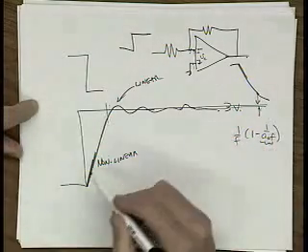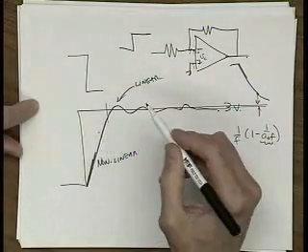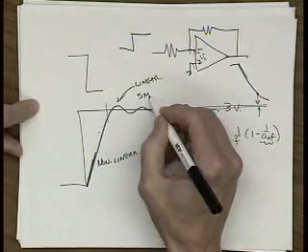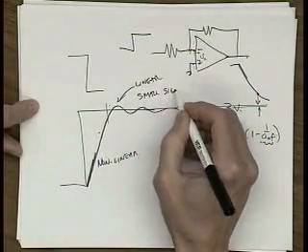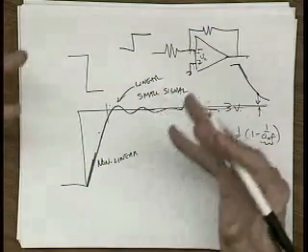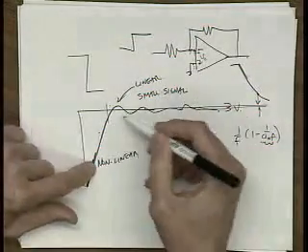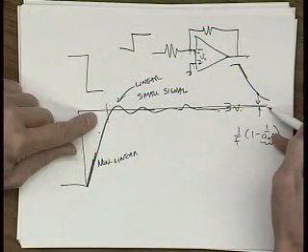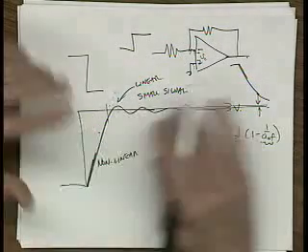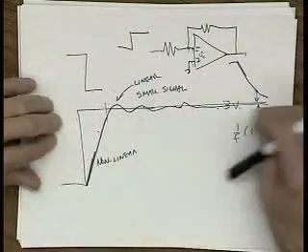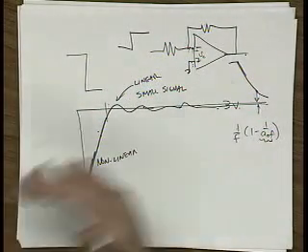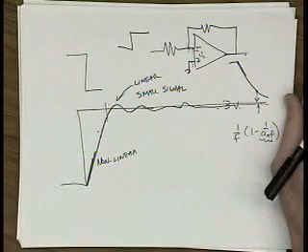Okay, so nonlinear settling, small signal linear settling, call this linear settling or small signal settling, because our small signal analysis works now. Okay, it doesn't work out here. And then finally, it's the static value that we finally end up at. Static means it's the value it's going to be forever afterwards, after all this time response stuff is settled out. So that's the settling response of an amplifier.